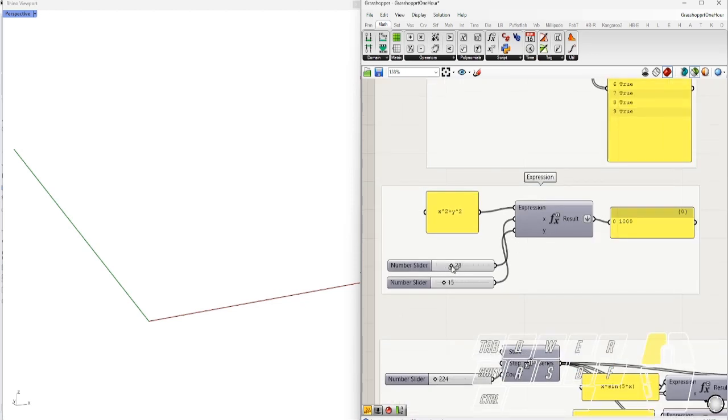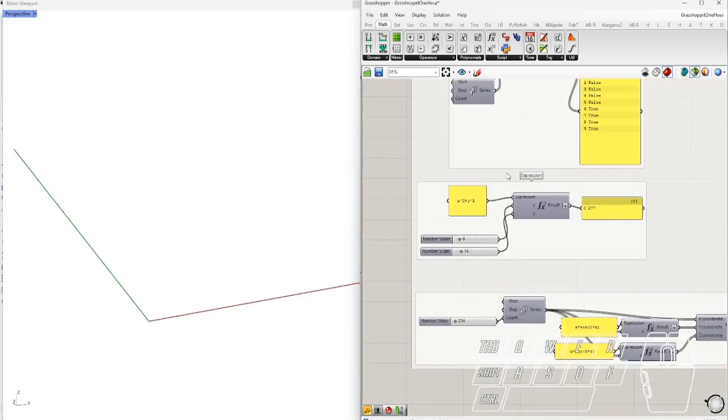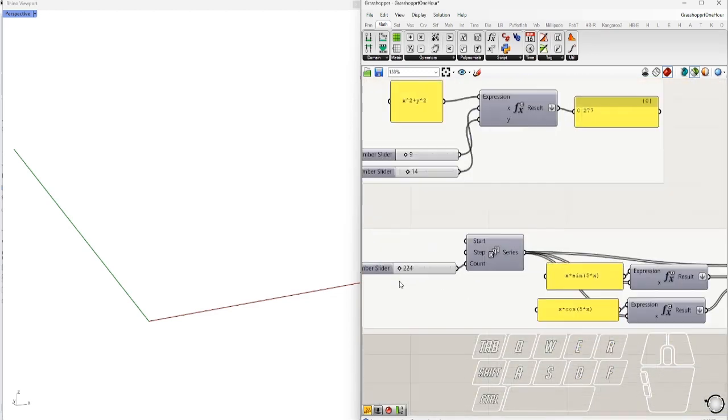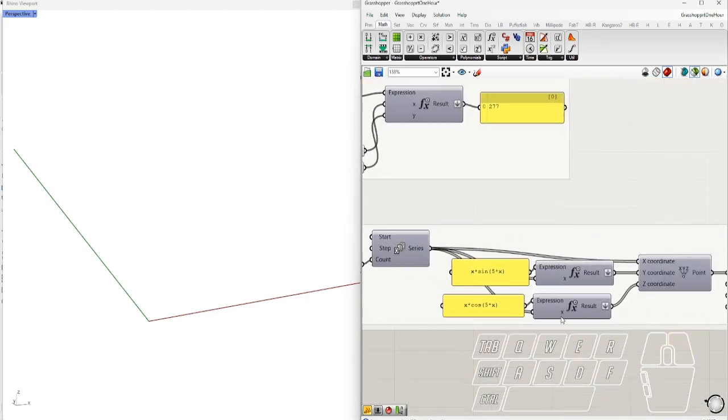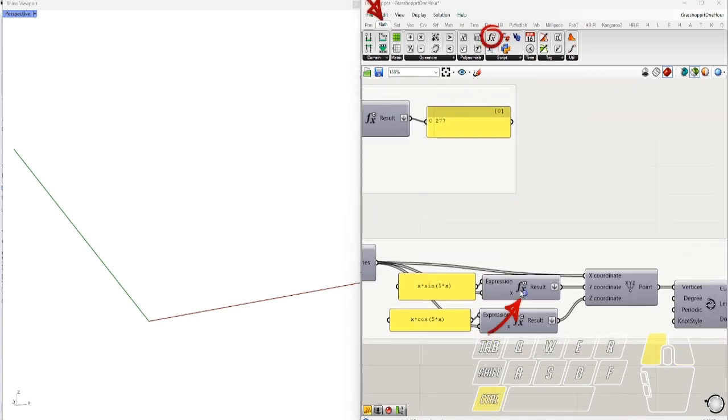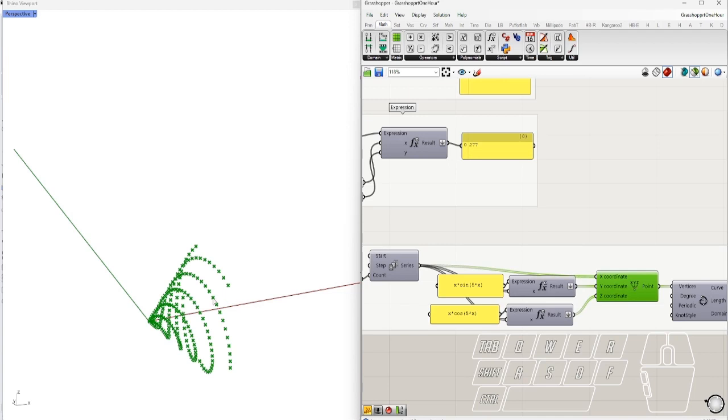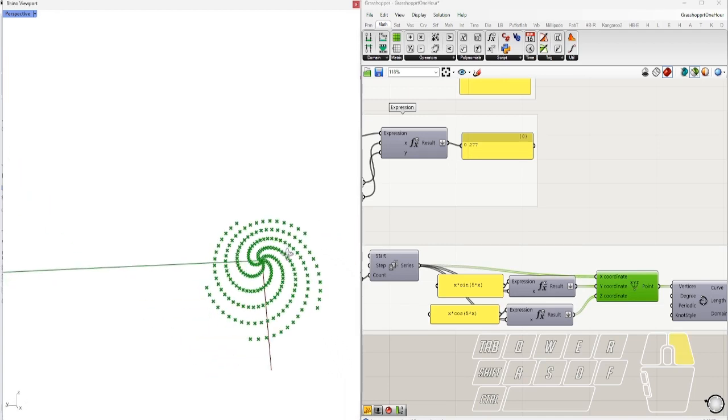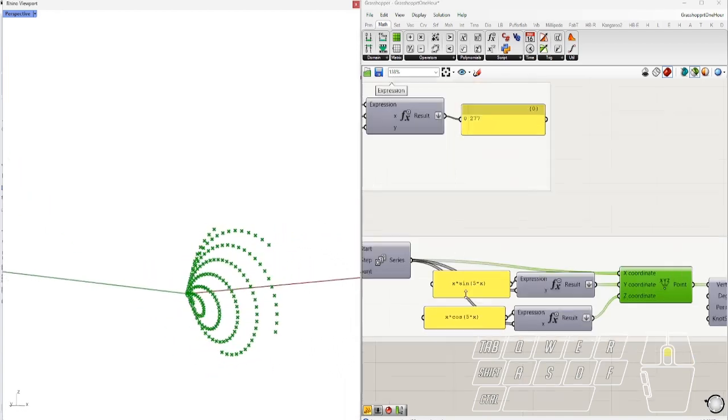And you could also turn it into geometric information, like here I'm gonna produce this helix-like geometry out of sine and cosine operations. I'm gonna use this if x to generate the coordinates, and I'm gonna link them through a spline.